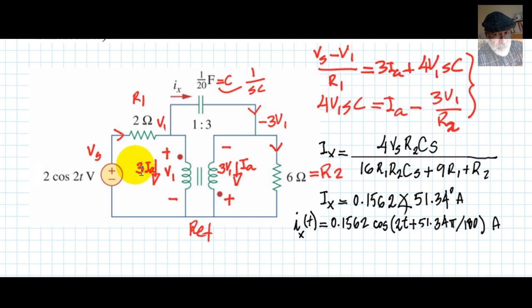If we use an RMS phasor, an IEEE phasor, which is usually what we use in the power industry, when we solve for Ix using that expression, we get the RMS value of the current Ix. That is a value an ammeter would read. But in this case, what I want is √2 times that value, which is the peak value I can use in the function of time.